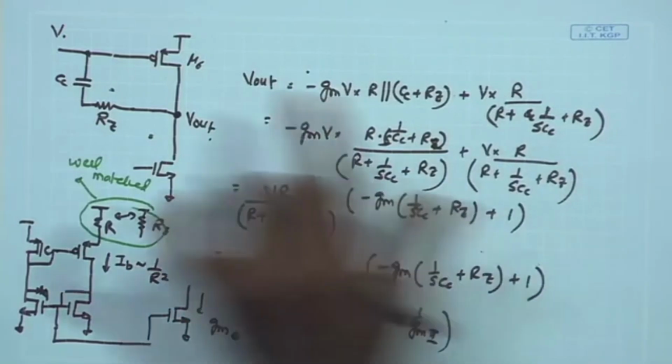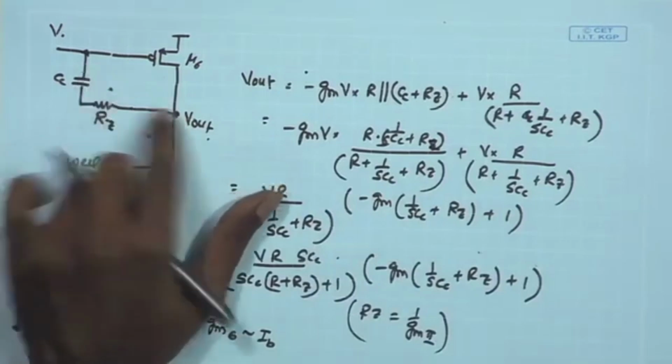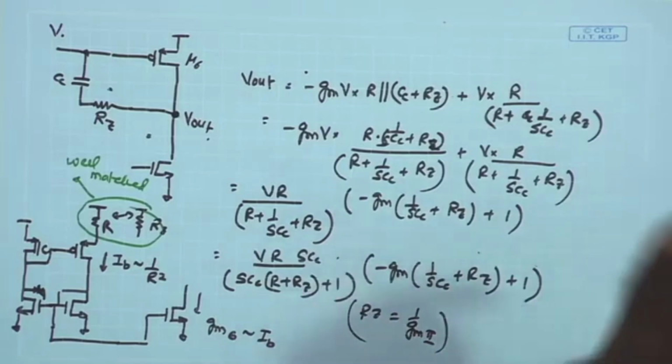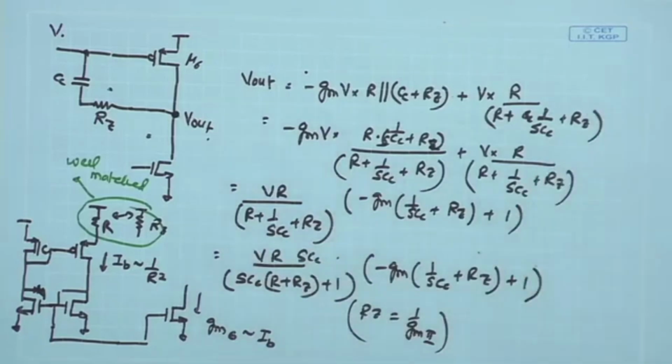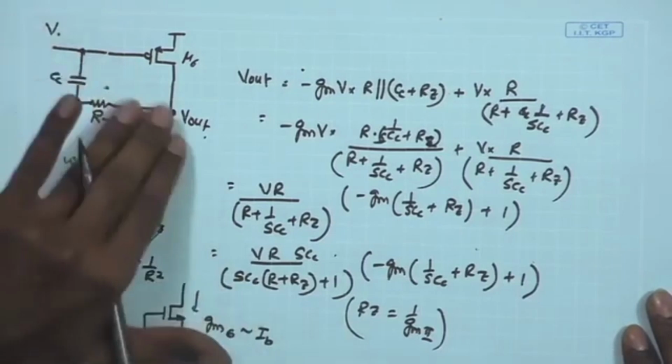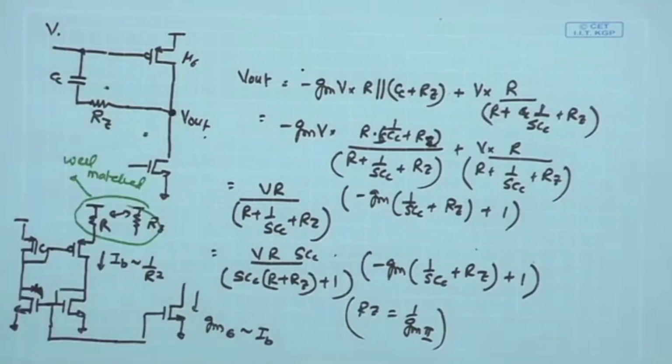Moreover, it is providing something similar to a shunt feedback, just like we have for the main amplifier. There also we have discussed that if the feedback resistor RZ or RF that we had in the op amp has a shunt configuration, the current mixed by that at the previous stage is relatively small. As a result, it is not going to have significant impact. And once again, we will revisit that noise analysis while we discuss the transistor level noise analysis, and there also we will try to justify in a little bit more detail that the RZ appearing in the shunt feedback does not significantly corrupt the input signal or significantly add to the noise of the amplifier.